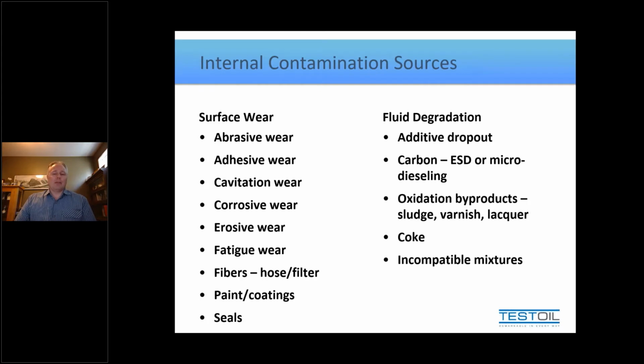Last but not least, though, when we say that there are internally generated wear particles or particulate being created, those tend to fall into either, like I said, wear or some other mechanism. So when we say wear, generally what we mean is machine wear, metal-to-metal contact, and there's a variety of wear mechanisms that are listed there on the left. But now down near the bottom, you'll see a few extras in there that aren't necessarily directly related to wear, but may be related to some of the components we install to help minimize some of these particulate themselves.